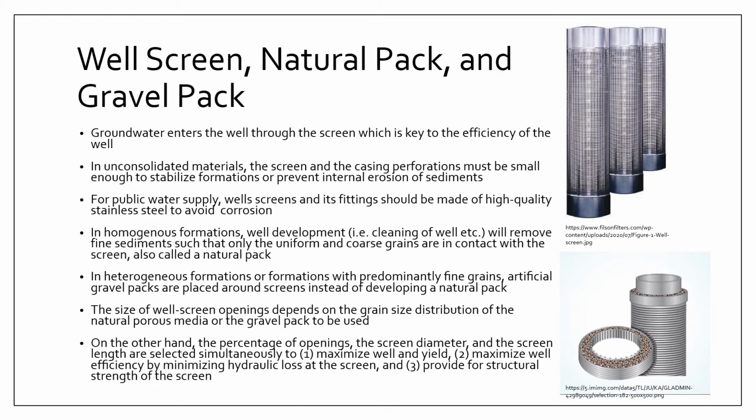Now, when we are dealing with heterogeneous formations, or typically your interbedded formations or stratified soils, or in aquifer formations that are dominated by fine layers such as silt and clay, we instead rely on artificial gravel packs. All right, so we just buy or import some gravel that is specifically manufactured or prepared for placement in your well.